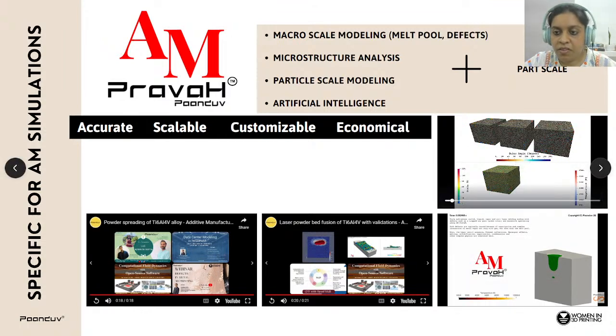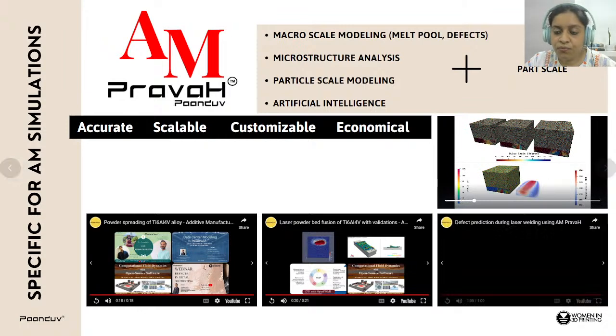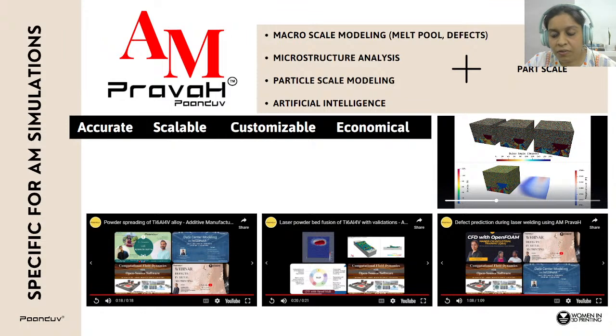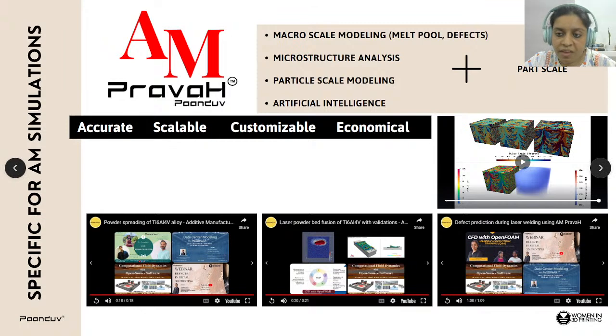The fourth one is the micro scale analysis. There are 4 scan tracks, 4 layers of laser hitting the part. At the bottom right is the temperature distribution, and you can see how the grains are misorienting themselves, merging together, forming and evolving the microstructure. These structures can be columnar or equiaxed, whichever you have given properties for. I mean, if you want to see whether the propagation will happen or not, you can change the properties accordingly in your part.